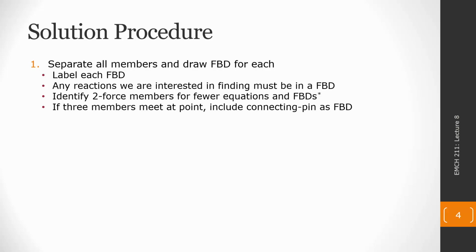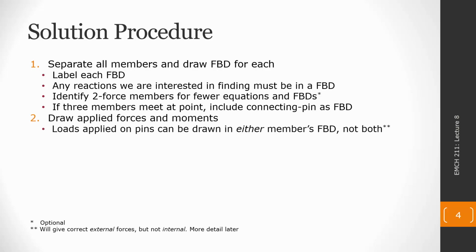On the free body diagrams, we need to draw all of the applied forces and the moments. So if we have these external forces and moments or couples being applied on a member, it's going to get copied exactly for the picture of that member.